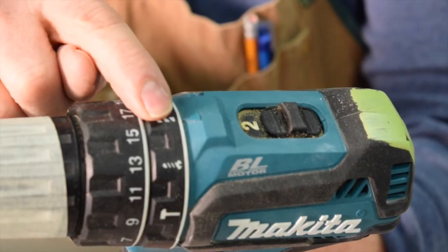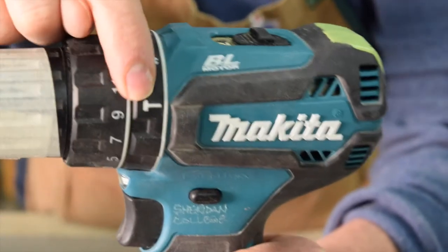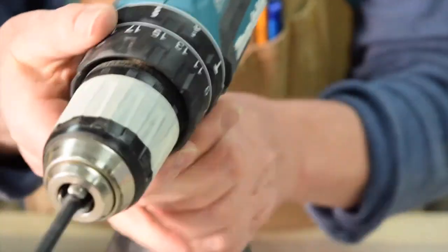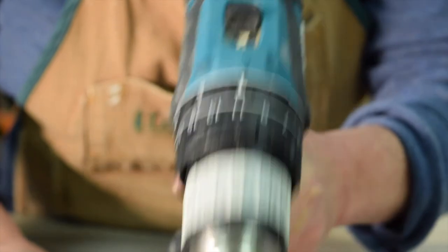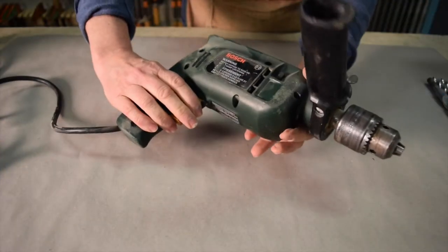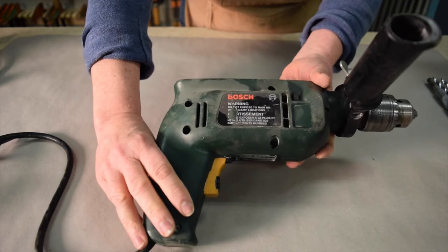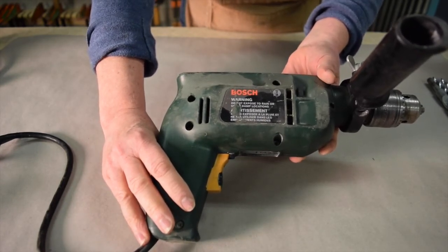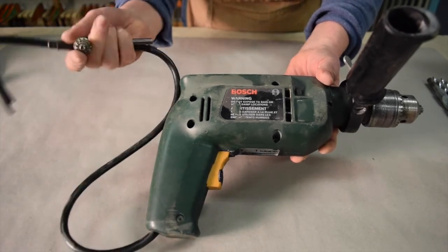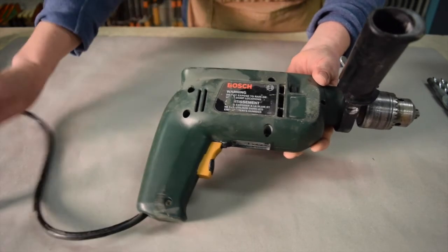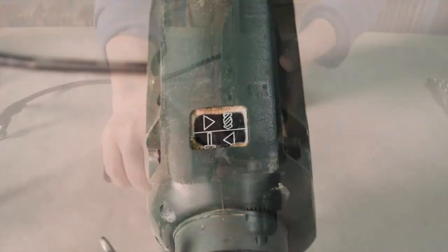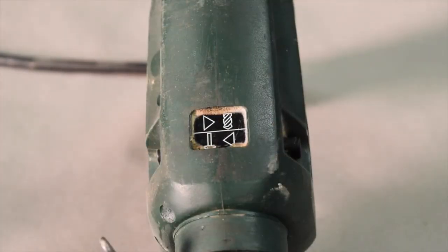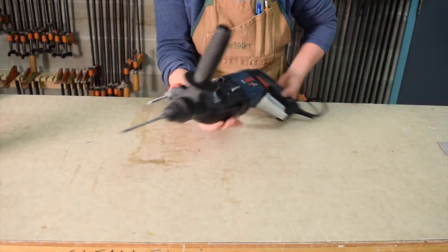And of course we need to use a hammer drill to drill these holes. It's typically just a setting on a regular drill indicated by the icon of a hammer. I don't find cordless drills very powerful for hammer drilling. I prefer to use a corded drill, and the corded drills will accept the masonry bits that I just showed you, and they require, of course, a chuck key to tighten the bit in place. If you look on the top, there's a button that indicates the drill mode and the hammer drill mode.